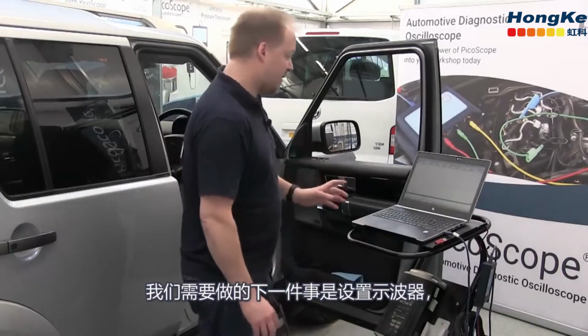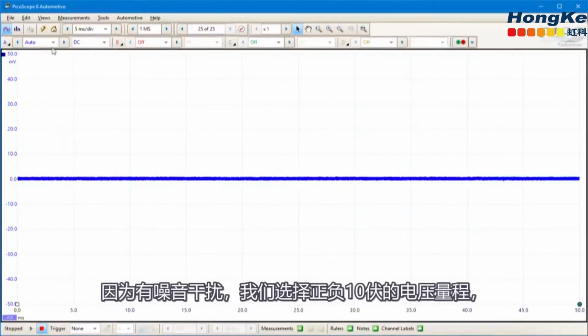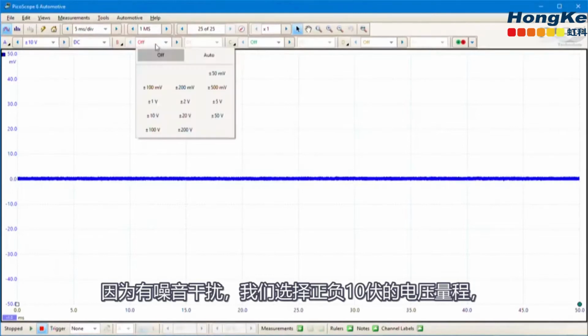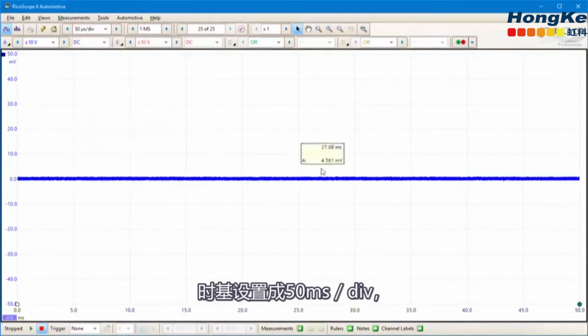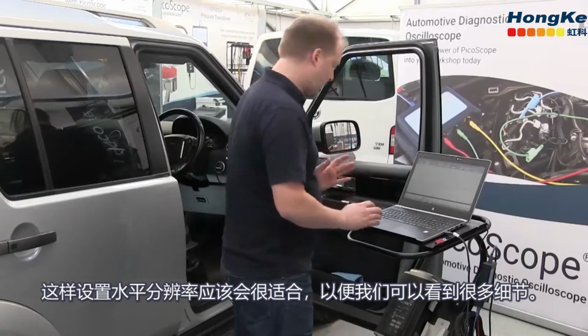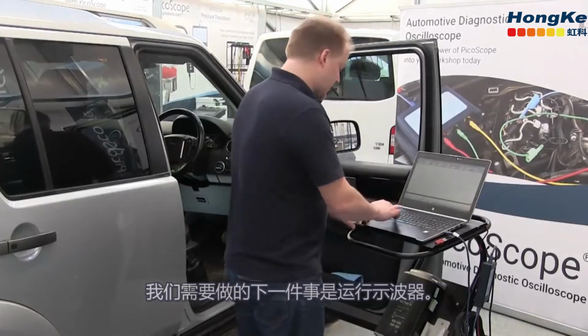So the next thing we need to do is set up the scope. To allow for noise, we're going to put plus or minus 10 volts on each channel, on channel A and channel B. We've got 50 microseconds per division and 1 megasample across the screen, which should give us a nice horizontal resolution so we can see plenty of detail. So next thing we need to do, we can just start the scope.